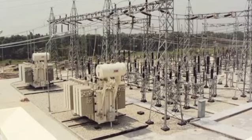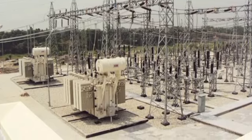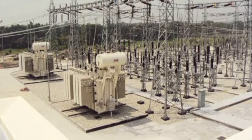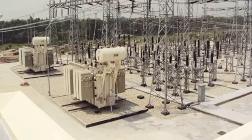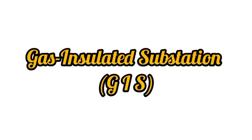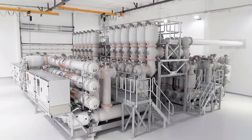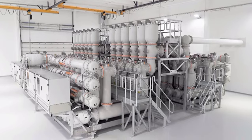Advantages: lower cost, easy to expand, and simpler design. Disadvantages: requires more space and may be affected by weather conditions such as dust, rain, and pollution. Gas-insulated substation, GIS. A GIS is a more compact and enclosed type of substation, where the primary equipment is insulated